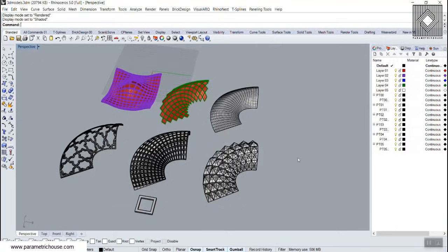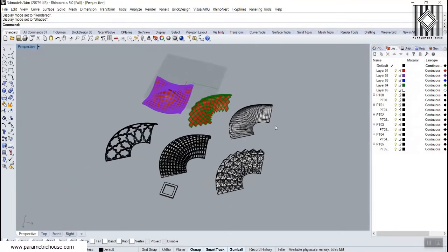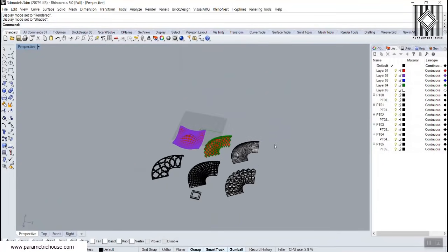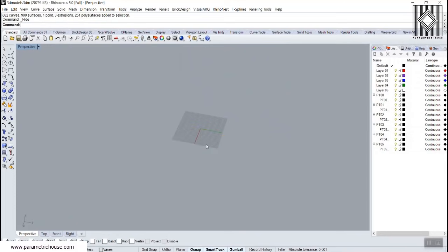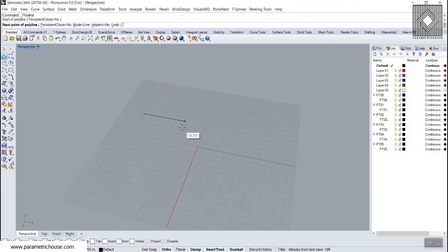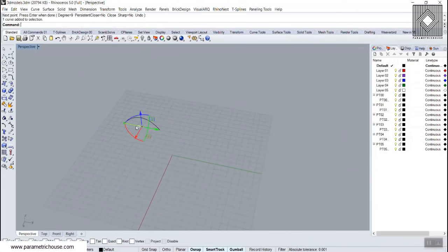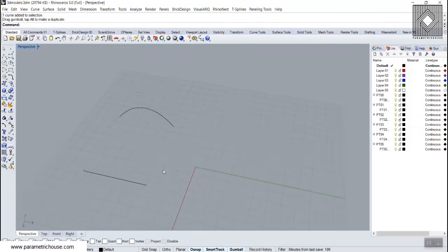Okay, to get started, first I'm going to explain how to produce, as you can see, this surface in Rhino. So I'm going to start with a simple surface and draw a line in Rhino. And we can also draw a curve. I'm going to use the Control key to bring this up and down here. So we can simply make a surface by lofting these two curves.